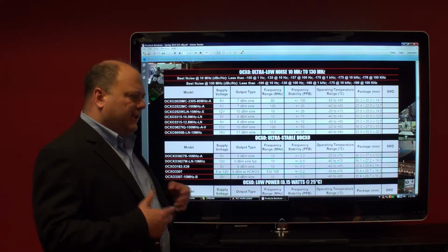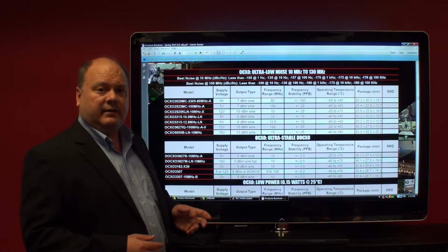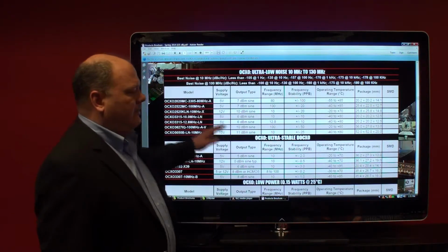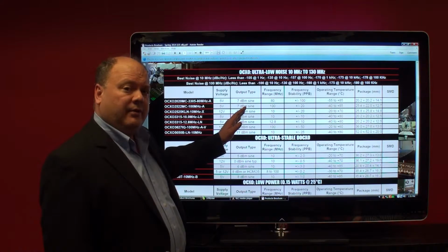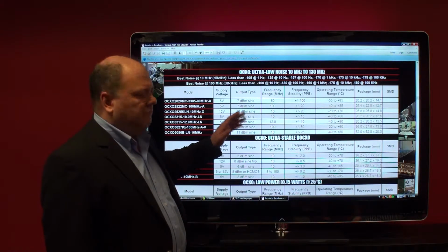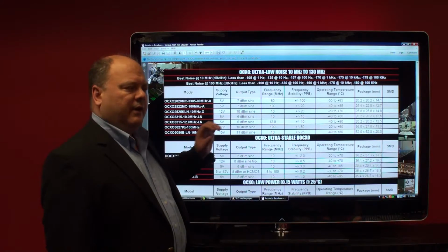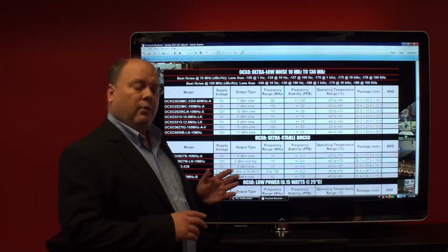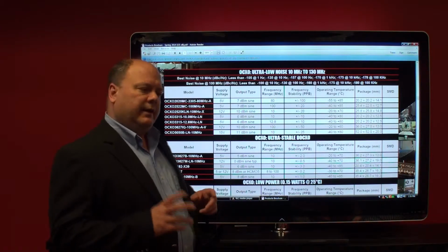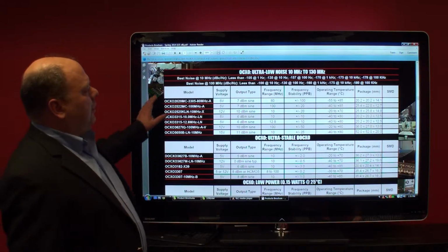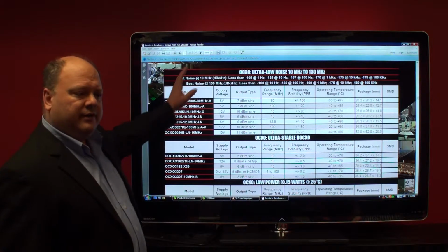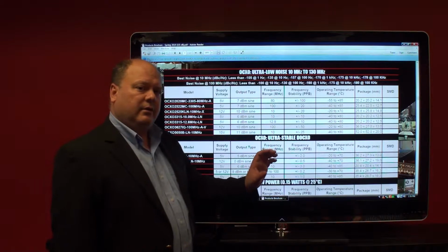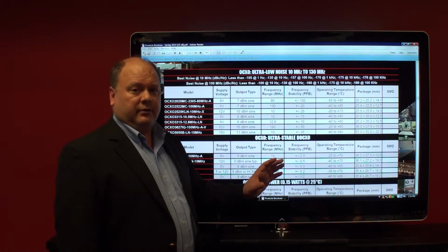There are a lot of electrical engineering reasons why that's the case, but usually when customers want to focus on getting a low phase noise OCXO, 90–95% of the time they're not as concerned with the frequency stability over temperature or the long-term aging. And here's the reason why. The ultra-low noise OCXO is located in a part of their product that is a reference for a synthesizer module.